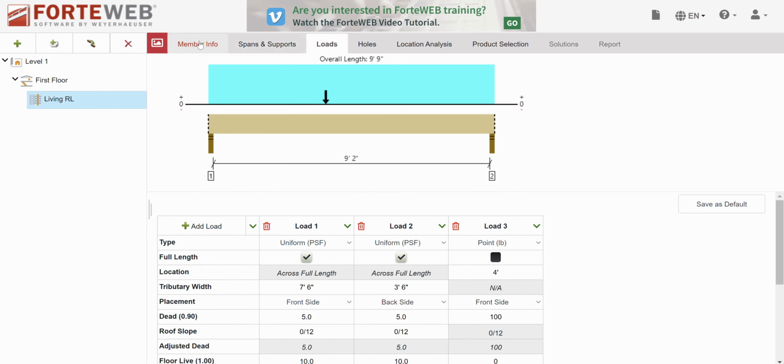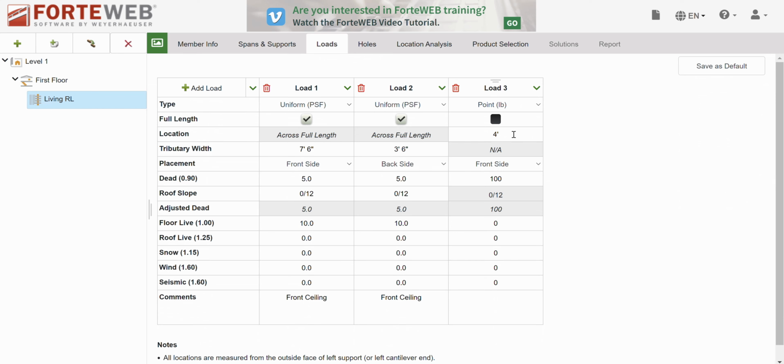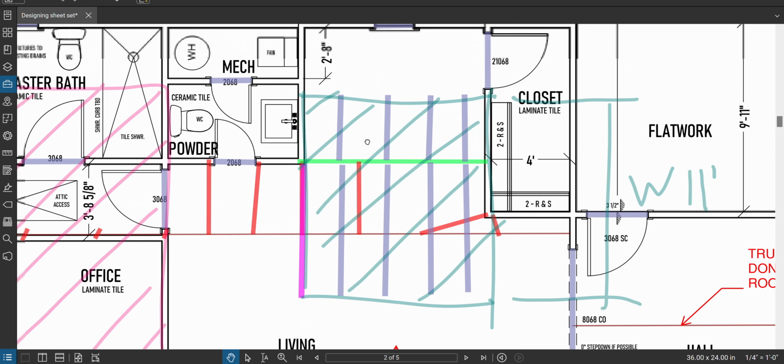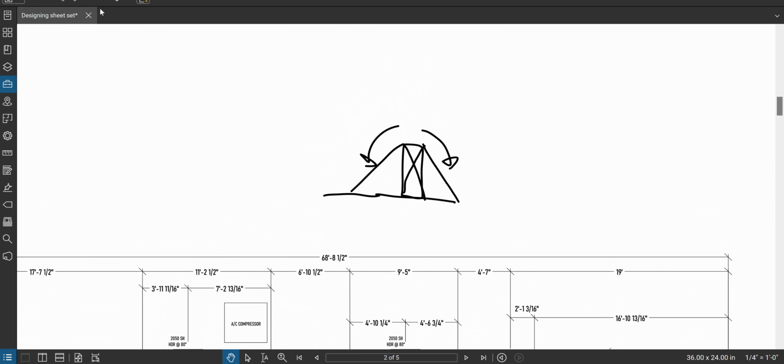So let's figure out how we're going to do this. I'm going to place this on top of the beam, most likely. Well, actually, I'm going to place this on the front side of the beam because of the way I have to attach this particular brace to the beam, and I will describe that in a second here. So I have approximately 4.5 feet from the top here, and my beam has depth to it. Let's say it's a 12-inch deep beam. I can't set this on the top of the beam because I went up a foot. So I'm going to end up setting it on the side of the beam using a ledger or something like that, most likely, because I need the height.